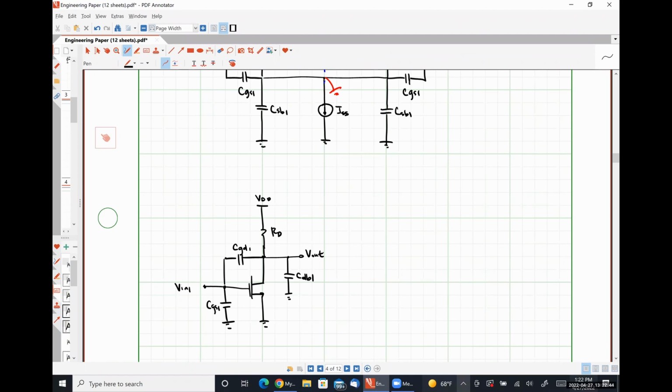So we would have two options in determining our high frequency model for this guy. Okay. The first of which is a direct method where we would have to take into account that our gate and our drain are linked together by that capacitor CGD1, which every other time we've analyzed anything like that has given us a second order system, or excuse me, a second order polynomial to deal with.